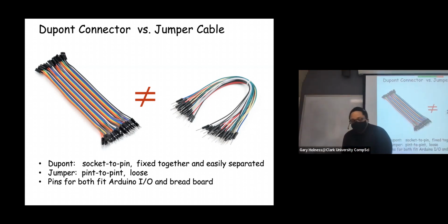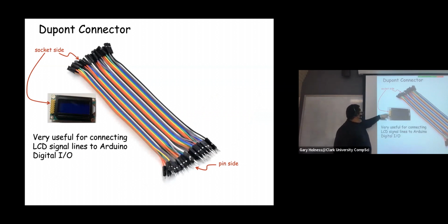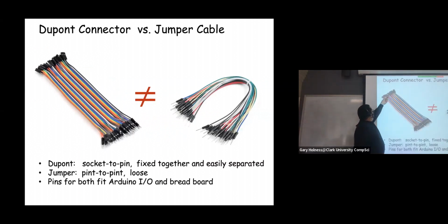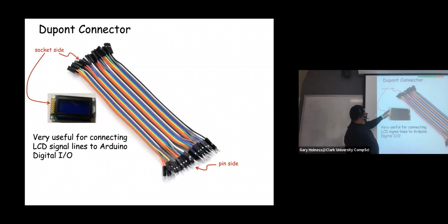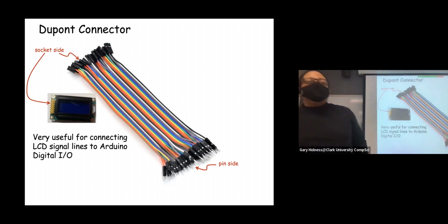And so one really strong recommendation for protocol when you're building your circuit, because you have 2 columns of 7 connectors, I would recommend pulling off 7 DuPont connectors and make sure they're still attached to one another, because that'll form a nice ribbon, and you stick these flush to one another and push it down into your header as one unit. Makes it a lot easier to do.